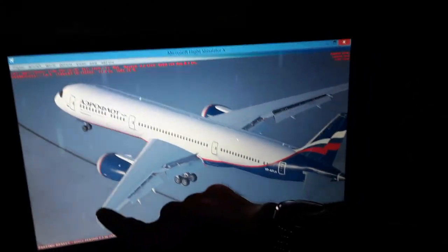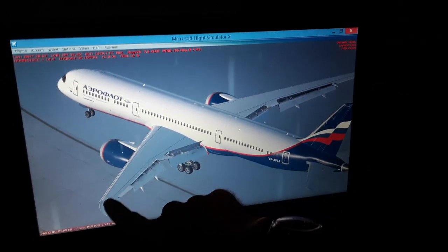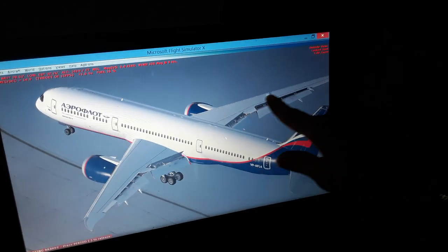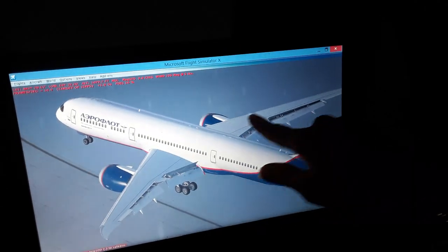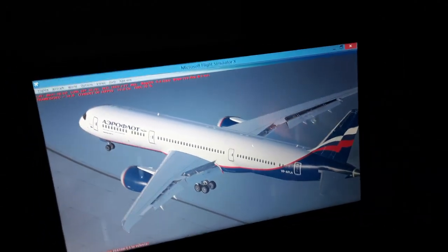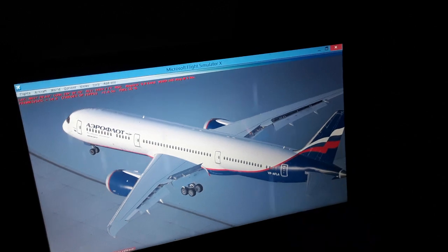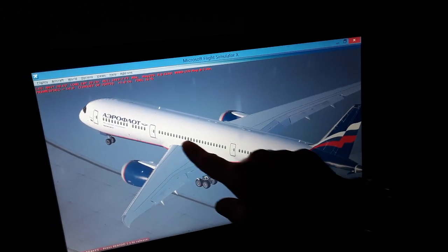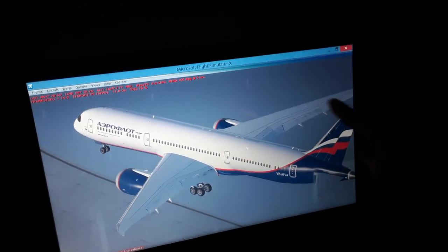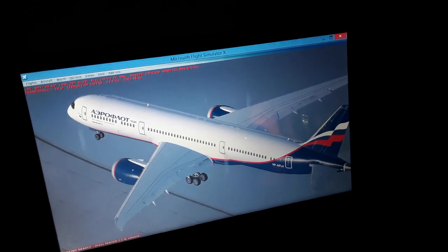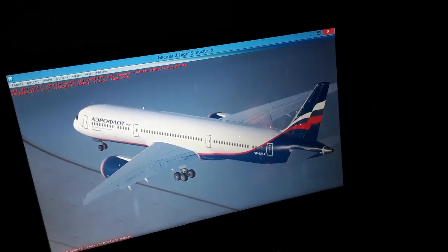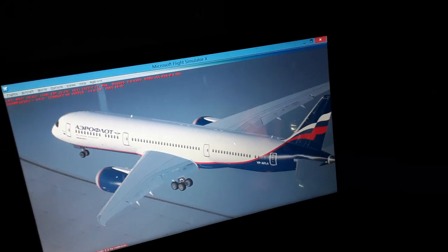We have the mean aerodynamic chord position, the MAC, which is about 23% of the mean aerodynamic chord of the forward wings, is where the maximum aerodynamic lift occurs in the forward wings. It's also where the stall will begin, all the way back. The airflow will become detached for a given angle of attack when we fly, and we're gonna lose the lift from the wings, so the aircraft's gonna be falling. So we need to avoid the stall during flight all the time.